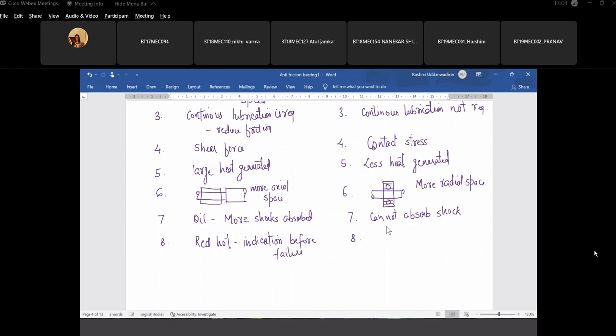Here, we have seen yesterday because of the contact stress, if there is a bearing, the maximum stress is somewhere near the periphery, not on the periphery, but inside this bearing, and the crack will start developing here, and gradually the crack propagates. We can see once this ball is completely fully cracked, we cannot see that a crack is developed inside. And since this contact stress will be uniformly distributed on all the balls, the ball bearing will suddenly stop working, and then there would be a lot of noise, which indicates that this is already failed.